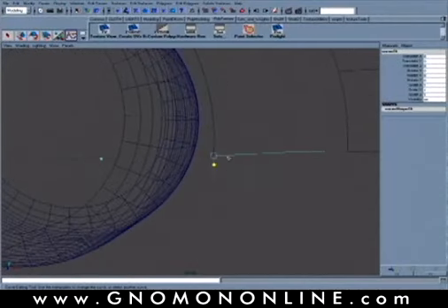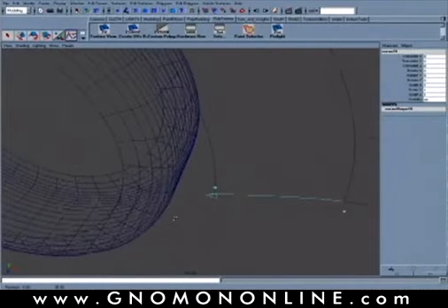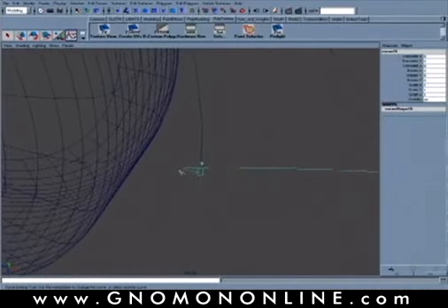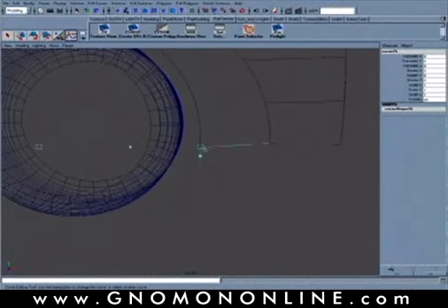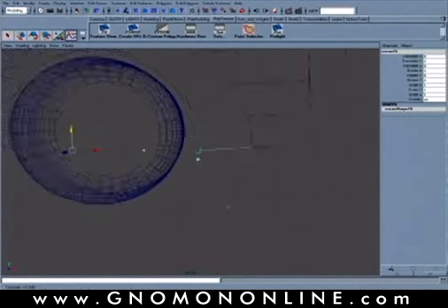And what I'll do in this case is align this up to the x-axis. And you can see that that flipped the wrong way. So I will select the handle going in the opposite direction with the curve editor. And now we have that smoothly aligned to our x-axis. Or we could opt to say rotate this and have it kind of bend down a little bit. Okay, so either way will work.